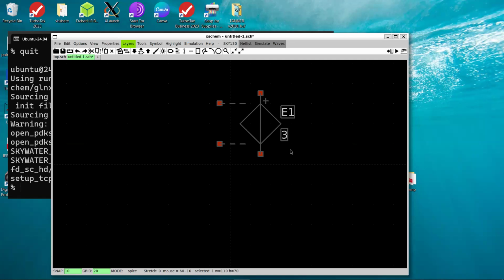Okay. So the OpAmp, although we've been showing 3 terminals, actually it'll be 4 terminals as well, because for that output, one of the terminals is basically ground, right? That's your reference. So we'll just keep it the same here. Because we're trying to create a symbol, just a wire is not enough. You need a pin, either an input pin or an IO pin. So typically in analog, you'll always keep IO pins because you have currents flowing in both directions.